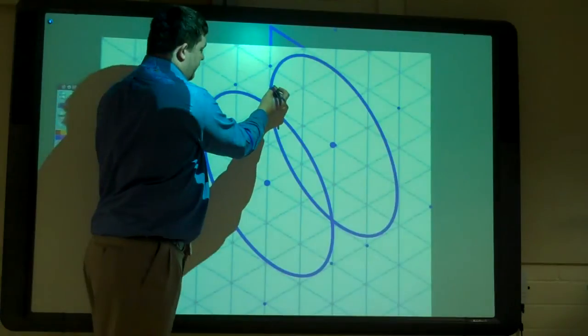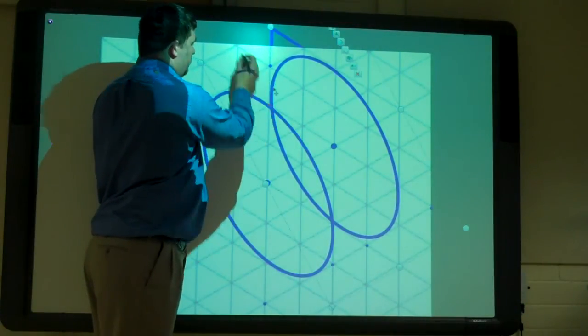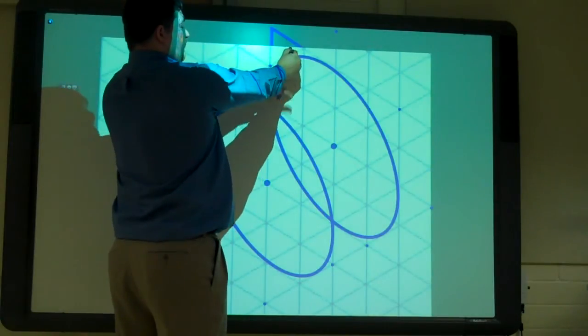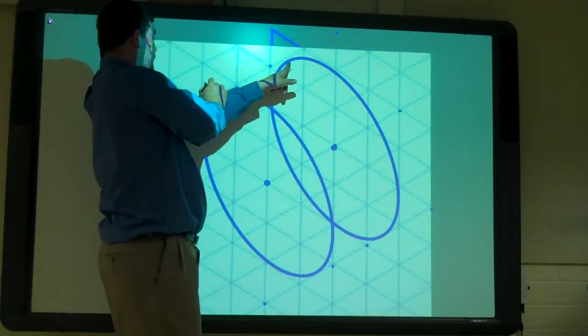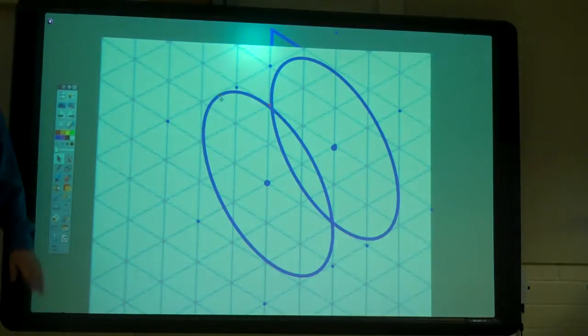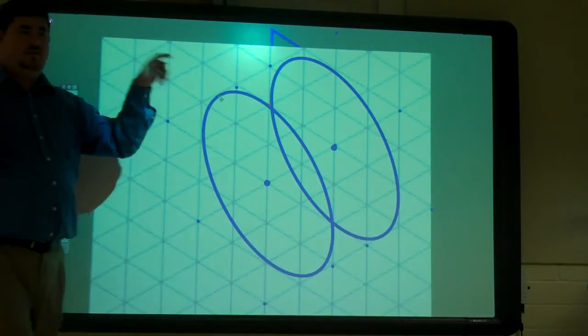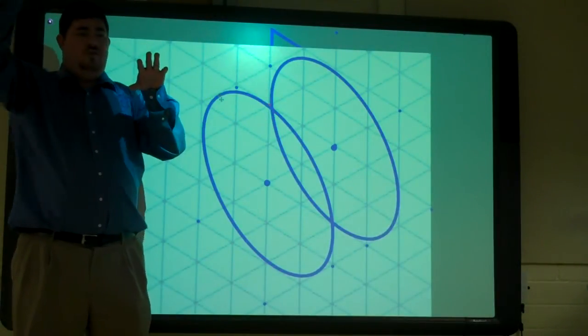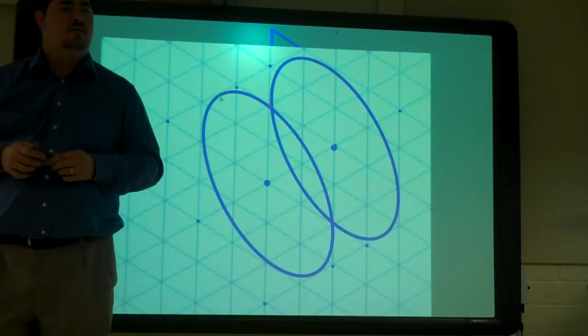Like mine is off a little bit. You just put your pencil on this, move your triangle up to it. Pencil over here, move your triangle up to it. Draw your line. It's better to make it tangent than make it perfect. So get it there, draw your line to connect it. It's done. Okay?